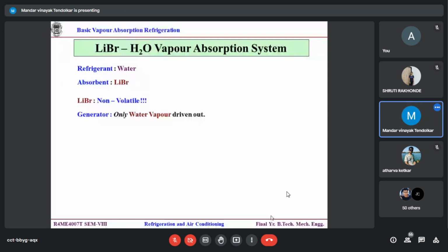Okay. So no rectification column. LiBr is always in liquid phase. Whatever you do to it, its boiling point is very high. So I will play only in liquid H2O and steam. Rectification column gets itself rectified. No need. Correct. So that is the biggest advantage. Simple. No rectification column, so not bulky. Cost wise smaller amount because no investment for rectification column. COP is higher. It is better than aqua ammonia.